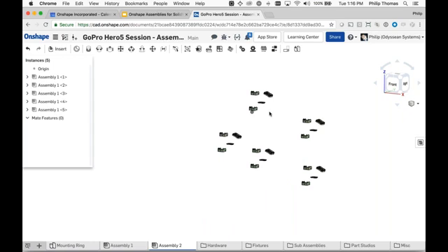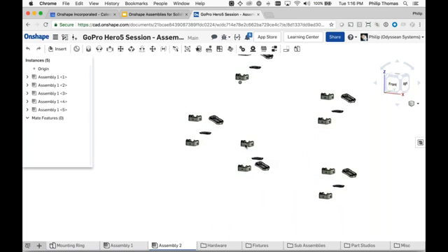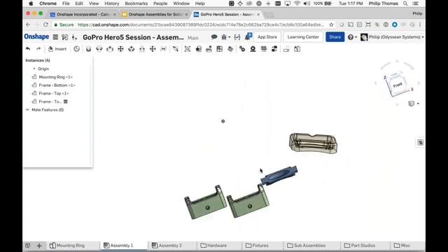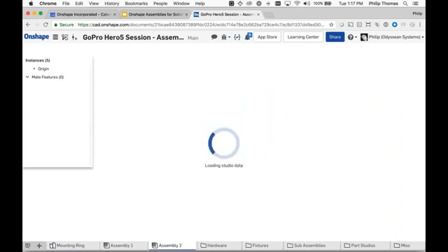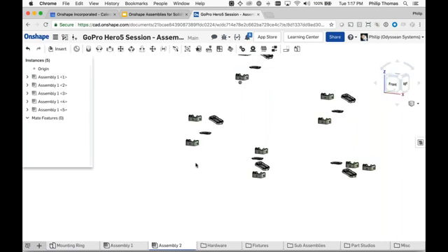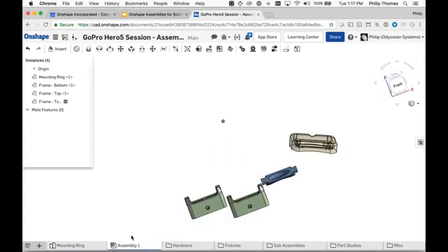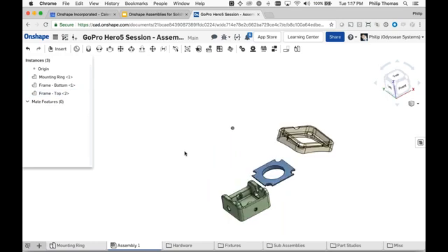why did all these sub-assemblies not appear in a row? The reason is that all the sub-assemblies are flexible, and each part can be moved individually inside the sub-assembly. Okay. Now, obviously, a change to geometry propagates up, but moving them here does not affect their positions here. So now the question is, what would affect the positions in the parent assembly? Time to start talking about mating. Let's get rid of these.